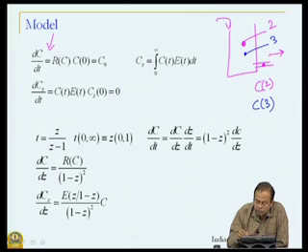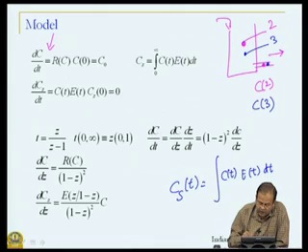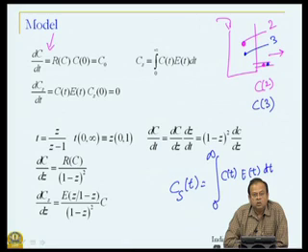So, what will be the total fluid concentration at any given point of time? This is my residence time distribution and this is my concentration at that time. Adding up all these fractions will give me the concentration at the exit of the reactor.